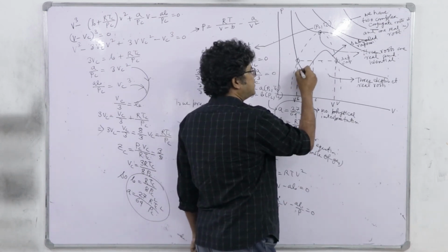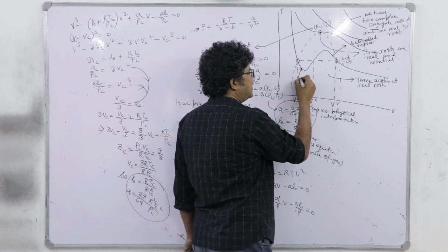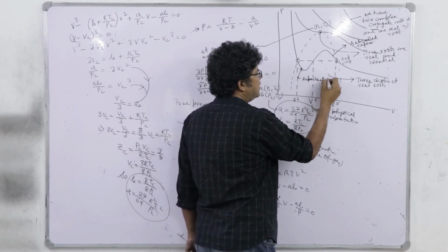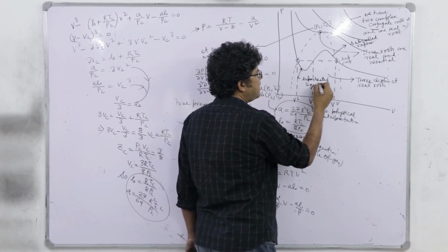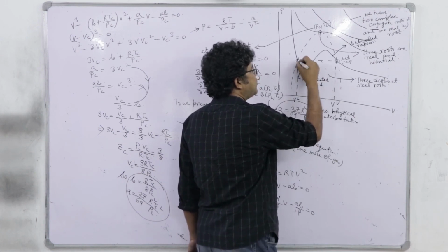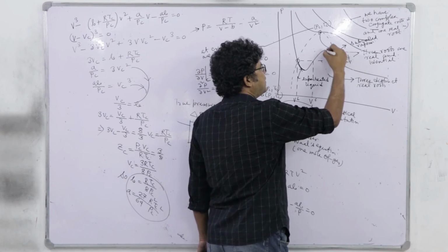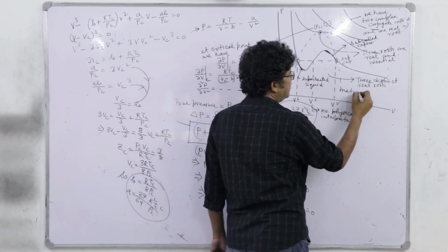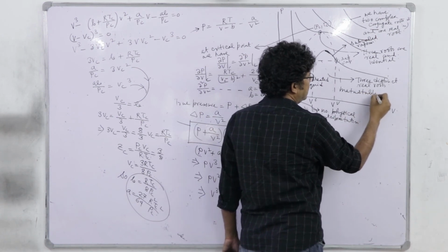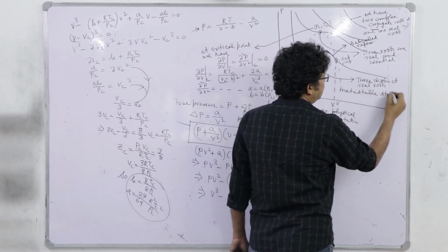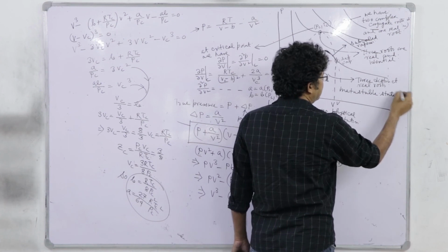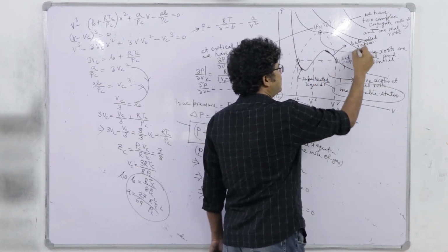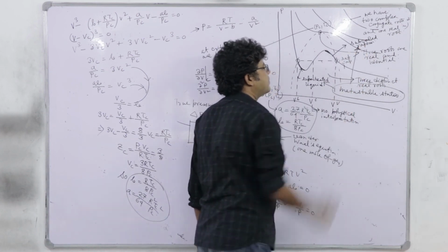And that is also absurd, but we call this state superheated liquid. So, this superheated liquid arm and subcooled vapor arm, both are metastable states. This is metastable, this is also metastable, right.